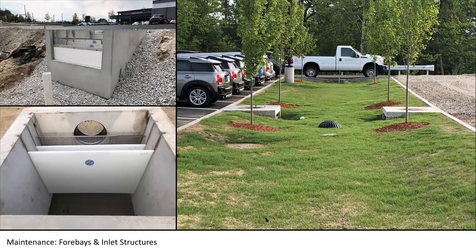And if you do have a high water table, that can be a challenge. Generally what happens is the groundwater will just drain into the underdrain and out into the storm drain. So if you don't want that to occur, you can always line these systems with an impermeable liner. That'll keep the groundwater from interfering with your engineered soil system.